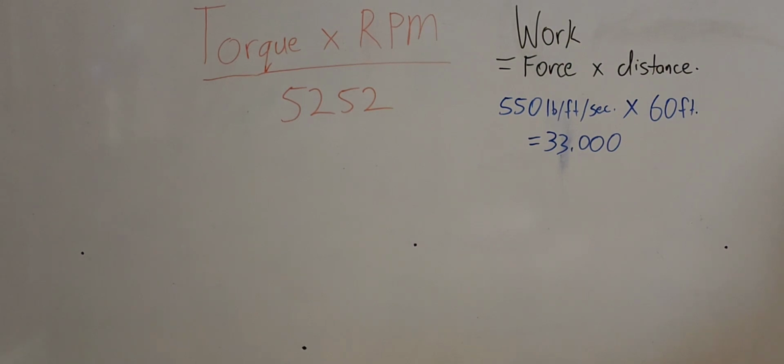The horse could indeed lift more, but it would put undue stress on the horse and would effectively limit its life, and also give the potential to induce injury. That is how the 550 pounds being lifted 1 foot per second for 60 feet came from. Now, the work is 33,000 foot-pounds, which is effectively moving 550 pounds 60 feet.